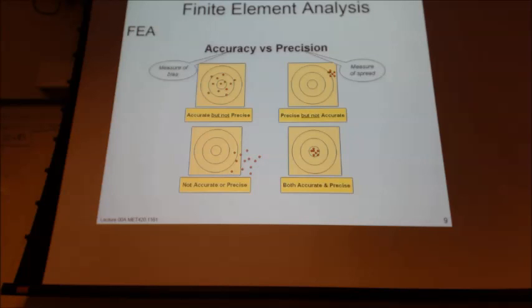So you have to make sure that you're asking the right questions and that you are providing the correct properties, geometry, and boundary conditions in order to get the answer that you're looking for. The accuracy itself will depend on the convergence, which is the refinement of the mesh. More elements, more nodes, but you don't necessarily want your whole geometry covered with the same density of nodes and elements as other parts. And so this convergence will help you reduce the error. And the accuracy will also depend on the boundary conditions that you apply and how they're applied.